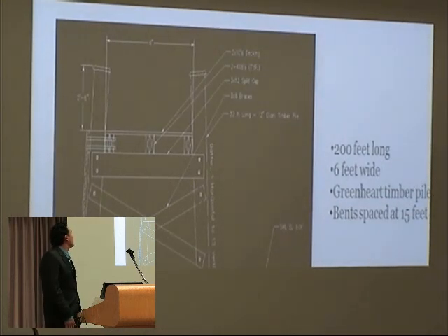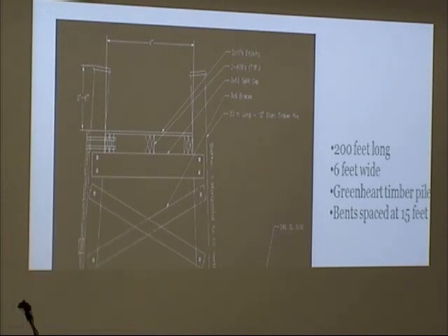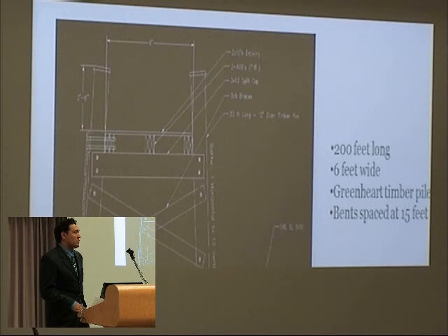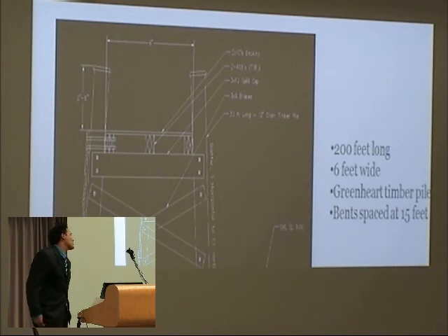and here we have the timber pier. The timber pier was asked by the client to allow access for small boats and also rentals for kayaks. The timber pier was a little bit different type of analysis, mainly because we haven't had too much experience with marine structures. However, for this structure, the design load was the lateral wave force.